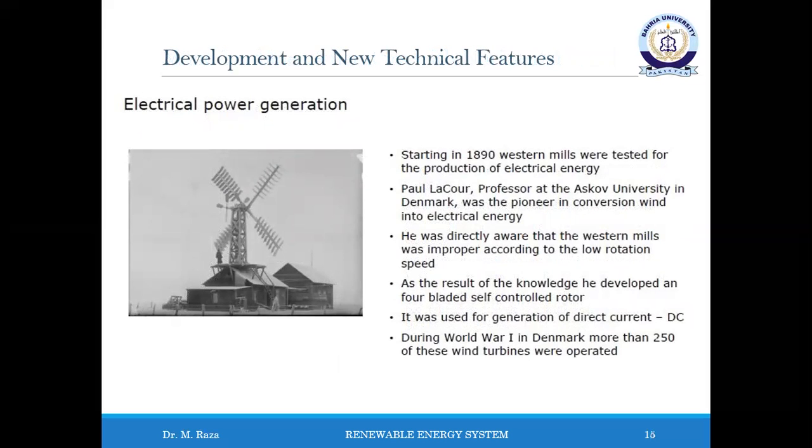With the development of the Western mill in the 19th century, a completely new era began for the application of wind energy. It reflects the industrialization of the wind energy application. The Western mill was not only the first wind turbine in industrial series production and made from metal, it was the first wind turbine with a completely automatic control requiring no supervision by a human operator. A sophisticated system of wind vanes served for yawing and protecting against overspeed during stormy weather.